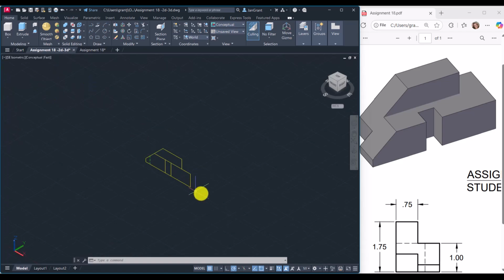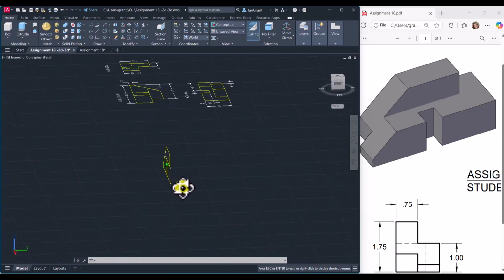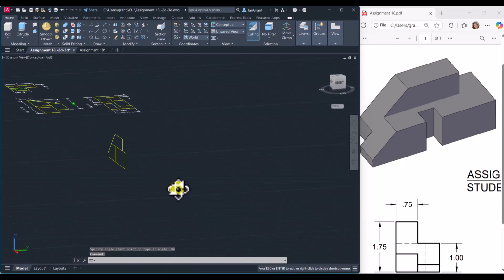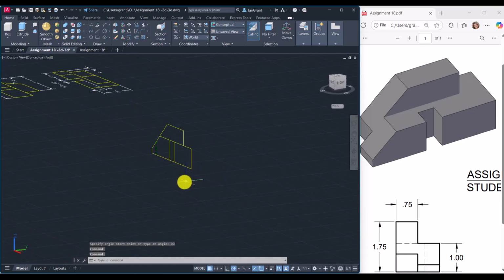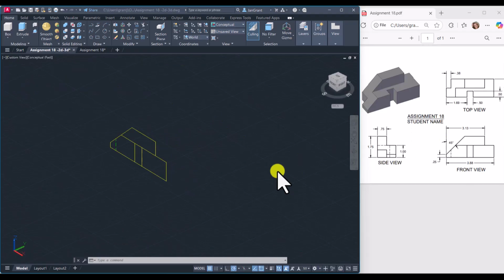If you hold your shift key and the wheel of your mouse, you can kind of orbit around and see, oh yeah, I used 3D rotate to take that 2D geometry and rotate it up. Now, this is where press pull, you need to make sure, first of all, that it is rotated. See how I can see that it's rotated. Okay, so when we use press pull, because we rotated it, we have to rotate our UCS icon, just like when we put dimensions on it. Usually I leave it flat and then I use press pull and then I rotate the whole 3D model. You can go either way, right?